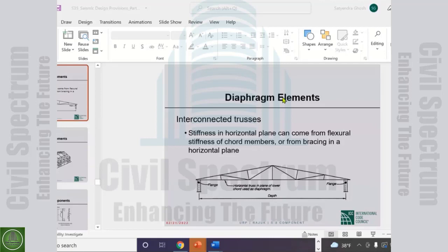Or it can be what we call design drift, which will be the elastically computed displacement at the top of the story minus the elastically computed deflection at the bottom of the story, the whole thing multiplied by C sub d, the deflection amplification factor, and depending upon what you are doing may be divided by the importance factor I. Now, if this design story drift is divided by the story height, that is called the design story drift ratio.